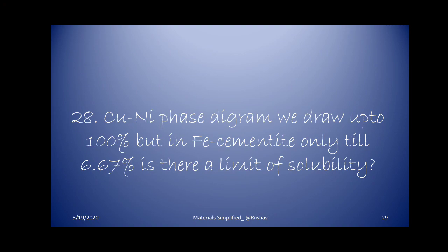Okay, and whatever comes, it substitutes one atom and replaces it, and this goes on. So obviously, if there is a replacement of atoms from their lattice points, complete replacement is possible. Say if A and B are there, B comes and replaces A, so this can go up to 100% removal of A, and we will only have B. But iron carbon is an interstitial.